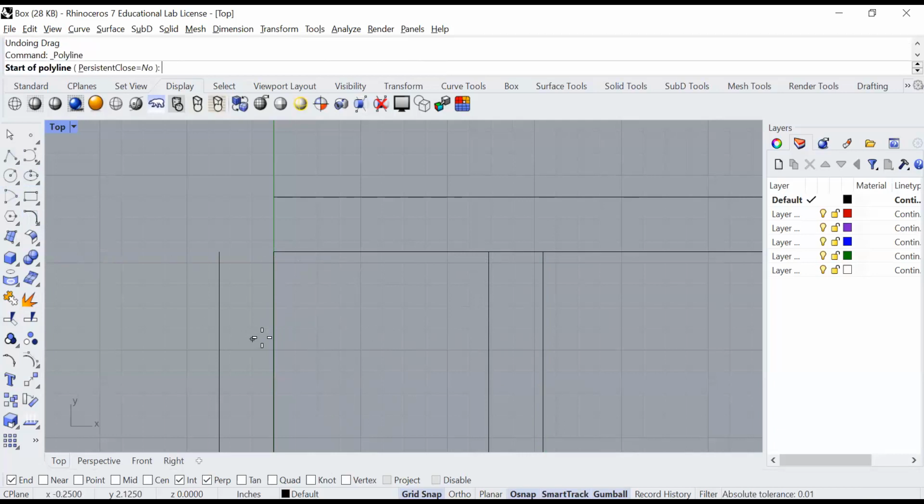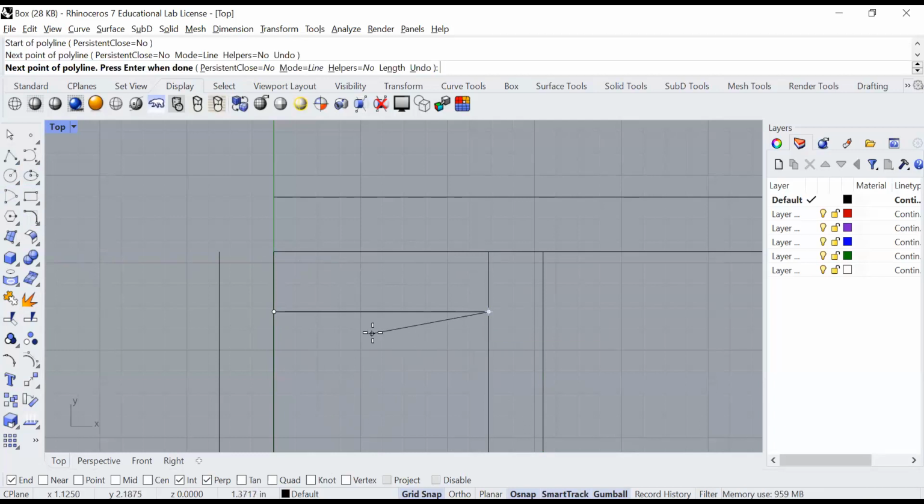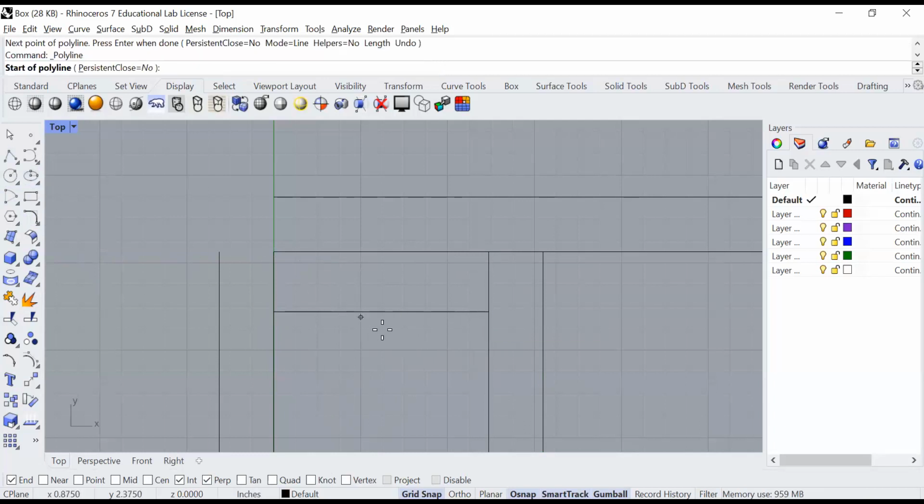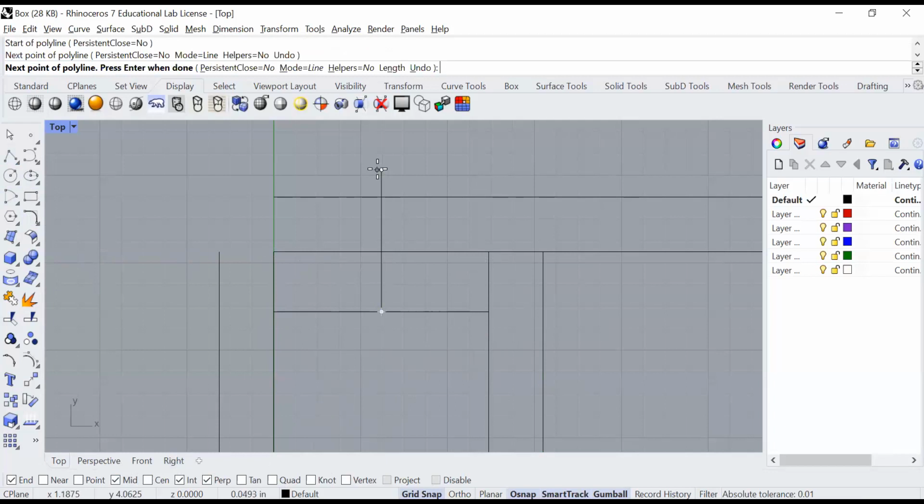Let's do that again. Again, a little bit of getting used to how you input stuff. I want to use a midpoint tool here and bring this up. I'm going to press enter, not escape. I'm going to make a circle, this center point, and its radius will be 0.375.